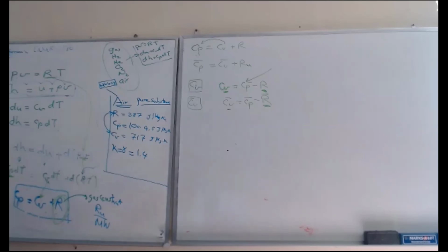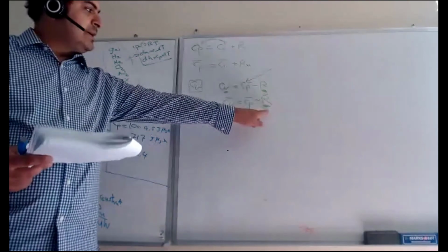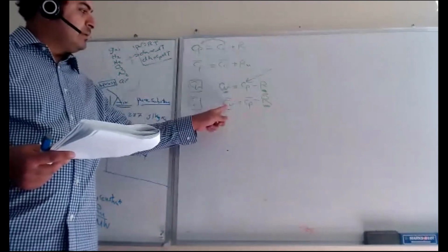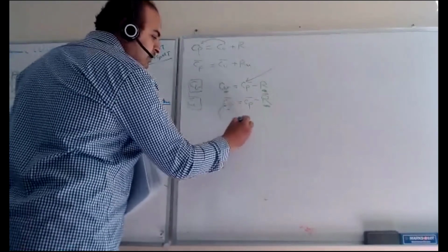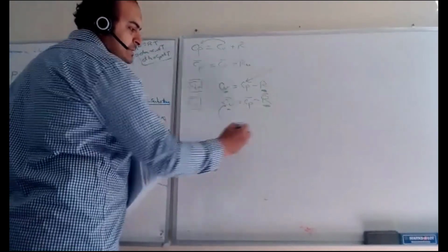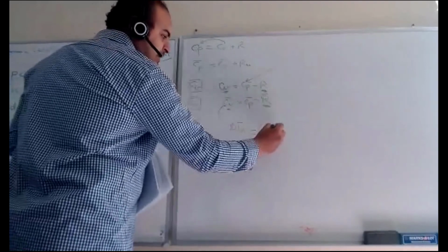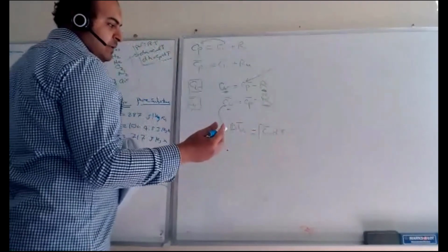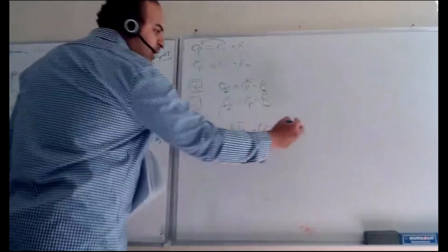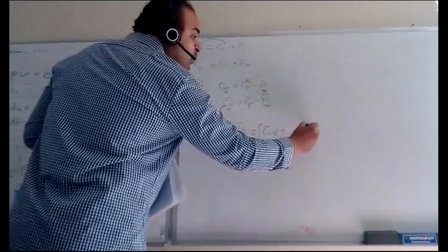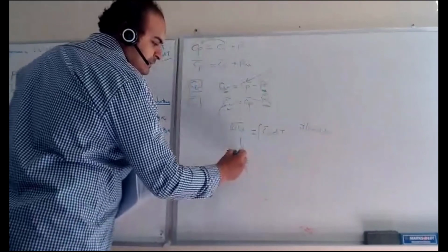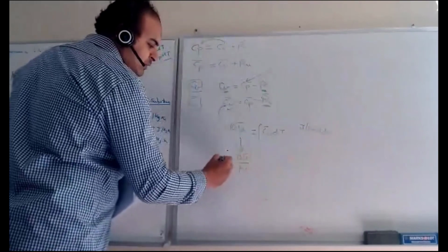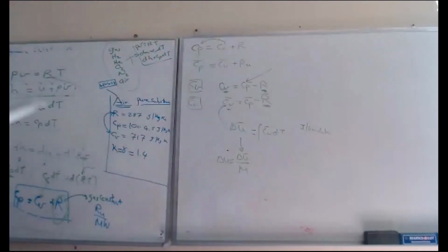All we need to do is subtract R universal. It will be Cv bar. So we use Cv bar to calculate delta U bar. Yes, it's the integration of Cv bar dT. After you get it, with a value in joule per kilomole Kelvin, just divide by molecular weight. It will be what you want.